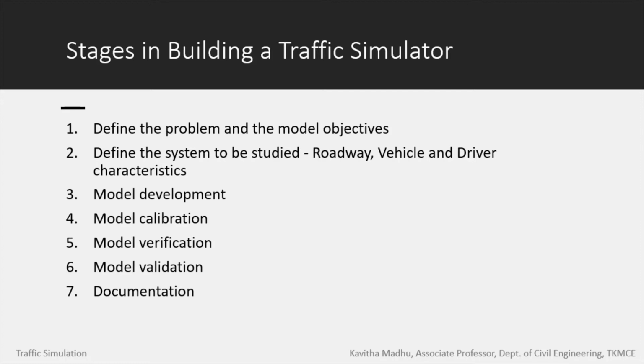Then comes model verification. So we have to verify whether the model is working properly. Say for example, we have an intersection, and we check whether all the lanes in the intersection are properly being used by the vehicles there, or whether the vehicles are running properly over the road. If they are colliding, we apply the car following theory. And even then, if the vehicles are colliding with each other or there are rear end collisions, all these aspects, whether the model is working properly, we need to verify.